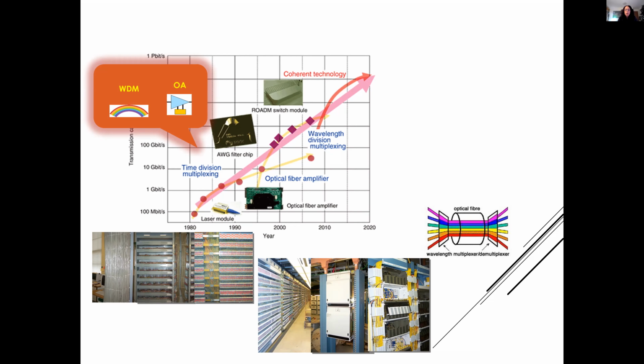The very first innovation was that we could transmit more wavelengths in a single fiber. So we use what is called wavelength division multiplexing, or in telecom you can call it frequency division multiplexing, transmitting simultaneously more wavelength channels inside the fiber. This came with the invention of the optical amplifier, where all the fibers could be amplified in one go.